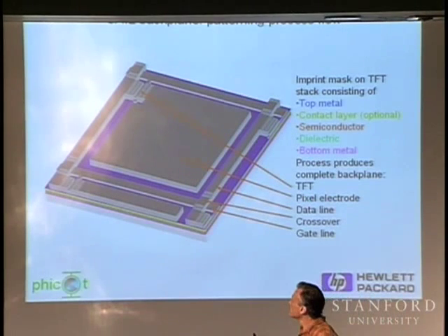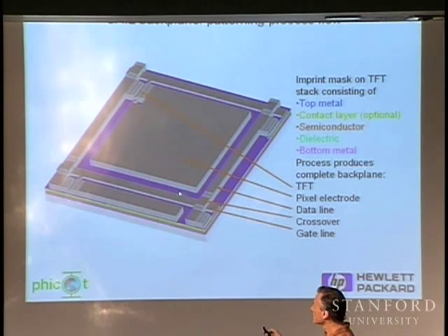Okay. So we have one side we call the gutter, and that's basically no imprinted material or very minimal imprinted material. Maybe it's a few nanometers that we de-scum off. Then we have the next height, which we're calling gate metal, and that masking structure is going to pattern those levels that ultimately we want to have at the gate structure.